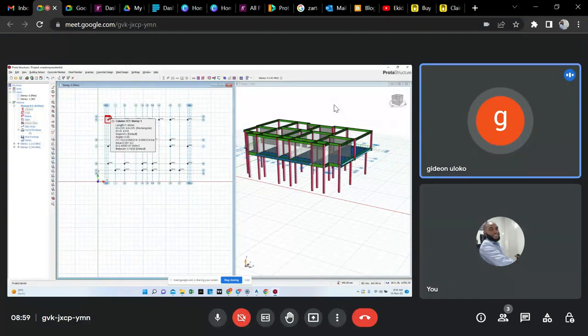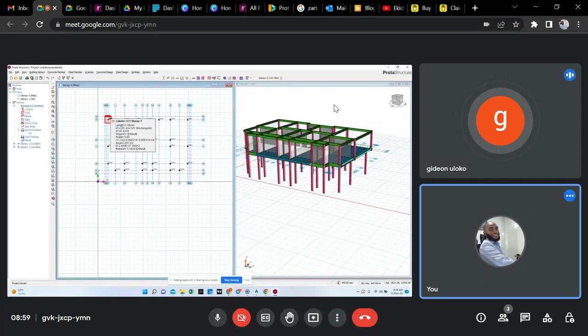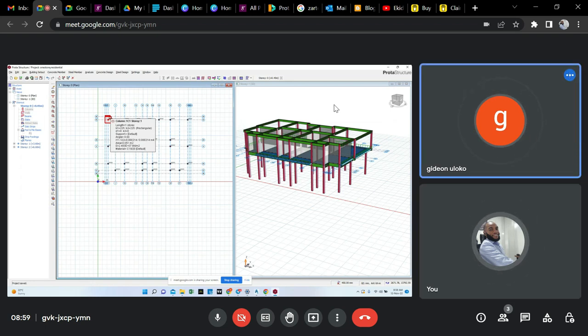If you try to do a strip foundation with Prota, you see that it gives you a width of footing along the entire stretch, basically the way a retaining wall looks, with a toe and a heel.